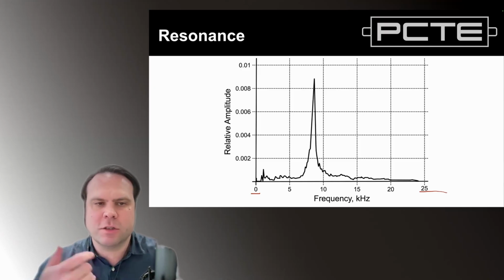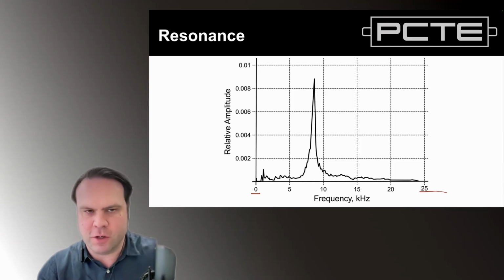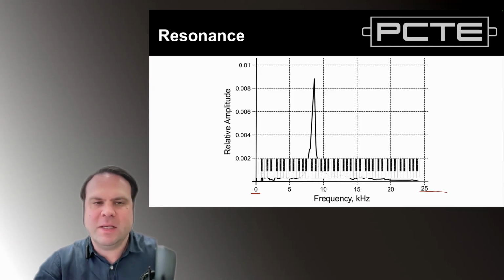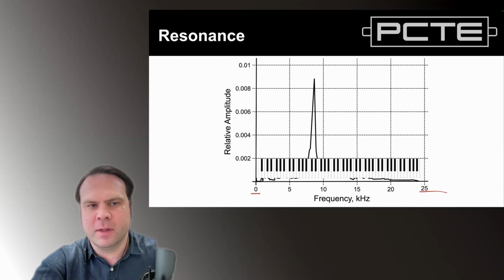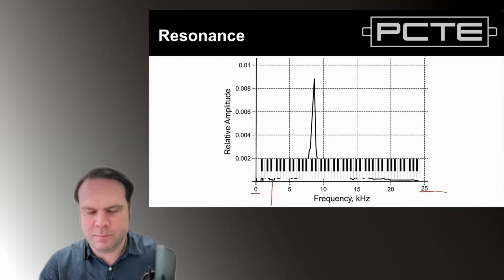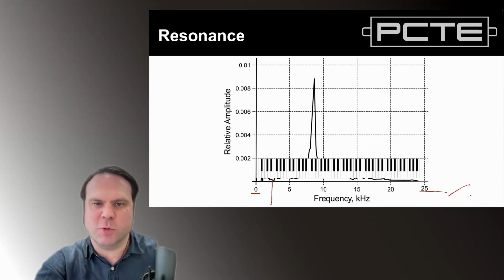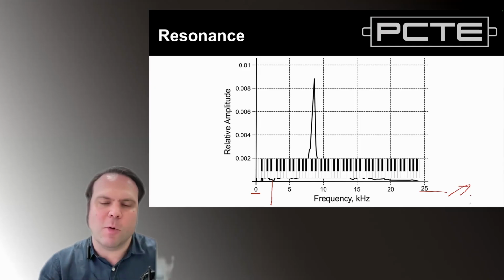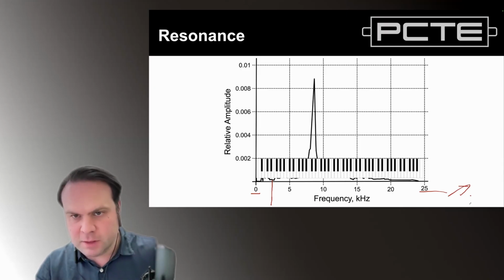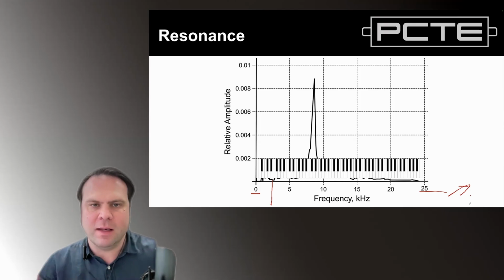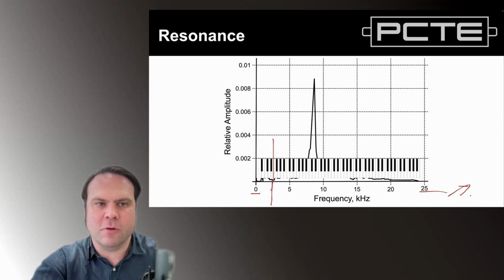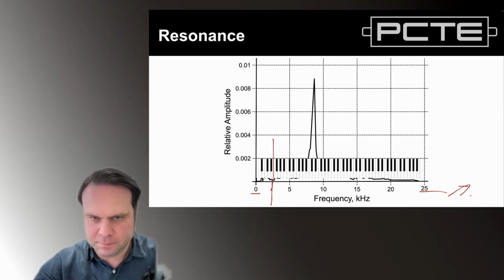So we actually want to use what's called filtering on this chart. Particularly, we just don't care about the lowest frequency content because that represents motion, not sound transmission. And there's a point above which we don't care about our high frequency, but it won't influence our test very much. So we're mainly concerned with limiting this low frequency energy during our test.